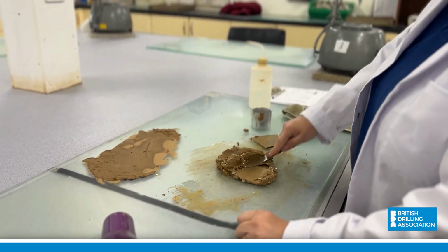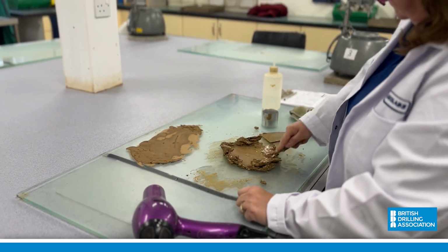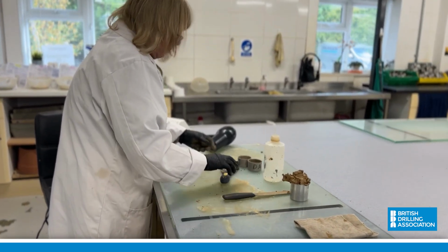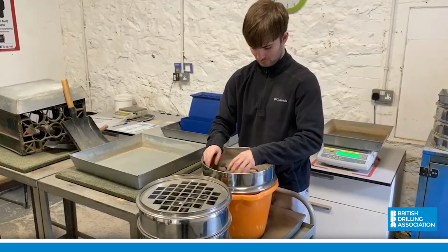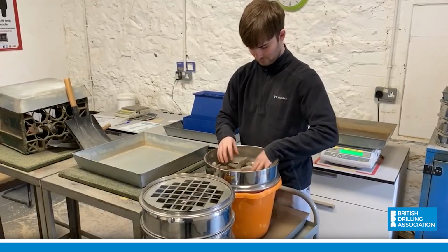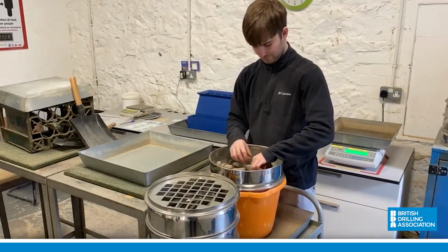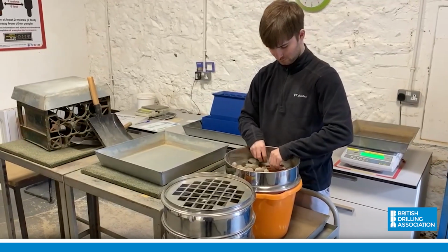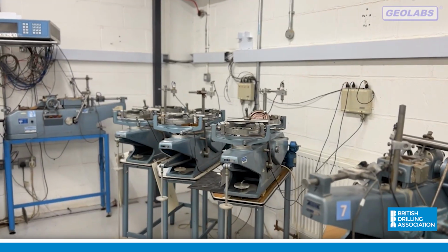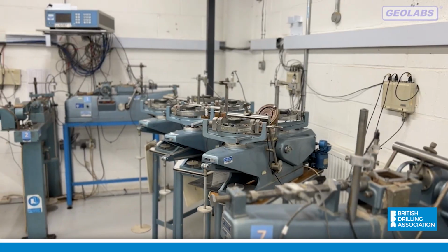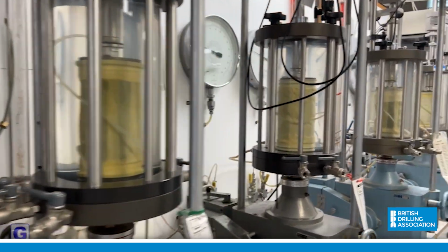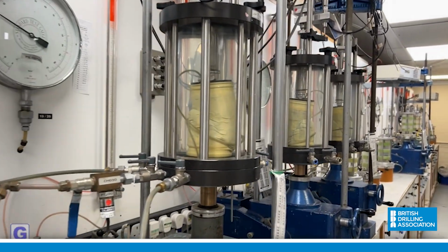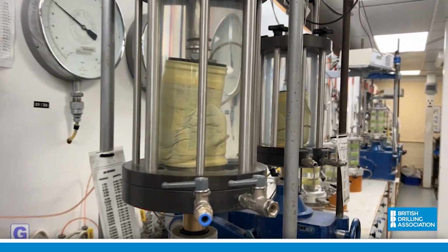Disturbed samples put forward for testing allow for classification tests, such as water content or liquid and plastic limit tests for silts and clays. Particle size distribution can be carried out on sands and gravels to provide an assessment of general material characteristics and soil behaviour. Undisturbed samples allow for consolidation testing, and triaxial tests can also typically be carried out. These can provide specific parameters such as settlement and strength.